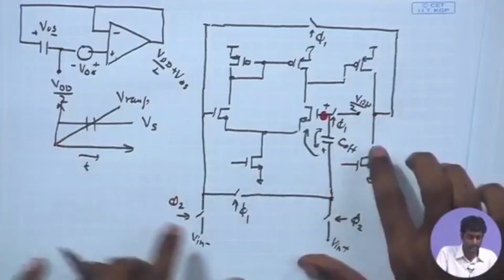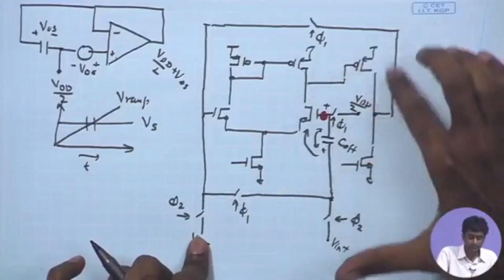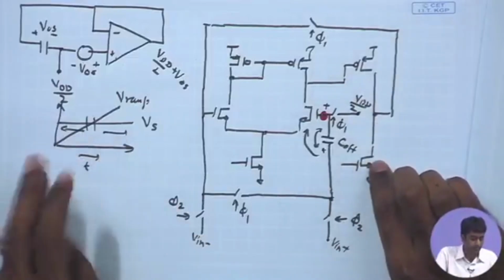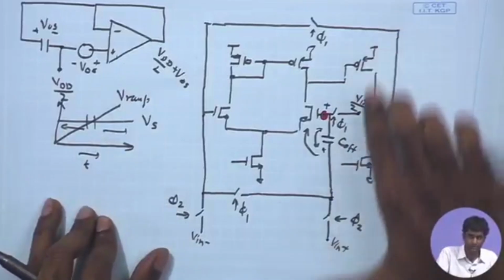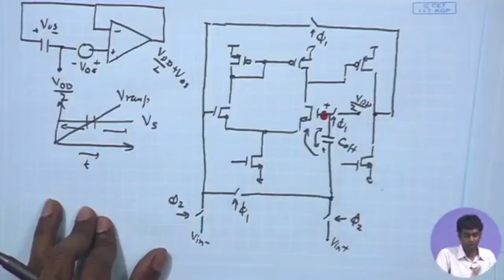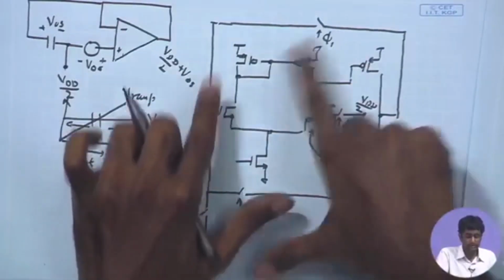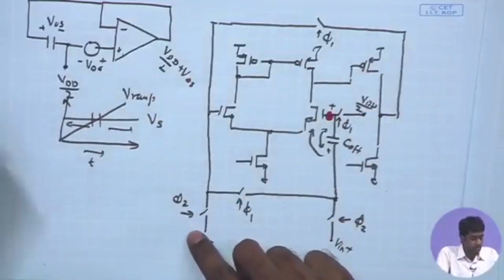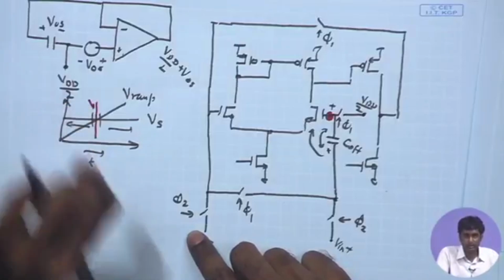What we are right now saying is that for the comparator output, we are mainly concerned with the output level going high or low. So, in this entire region the output will be high or low, VDD or ground. Therefore, we need not consider the saturation region operation and appropriate DC bias point for this one. All we want is as soon as V ramp approaches Vs, all the transistors should be in saturation, so that the decision regarding the transition should be taken at the right time step.